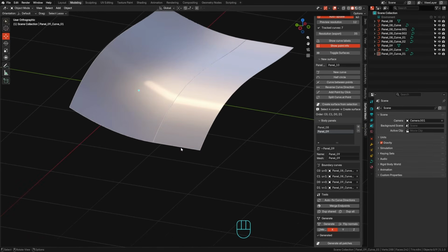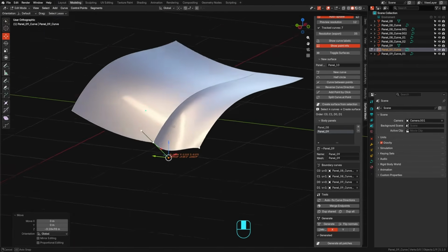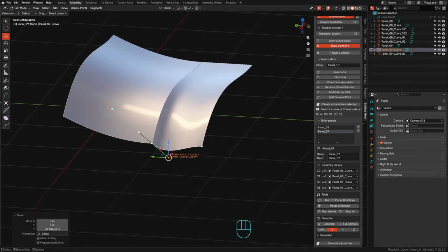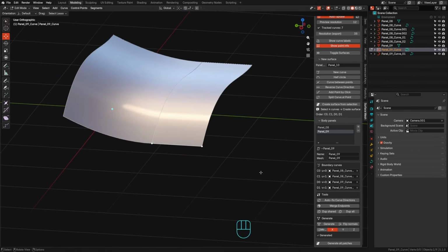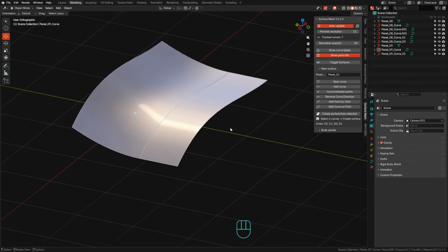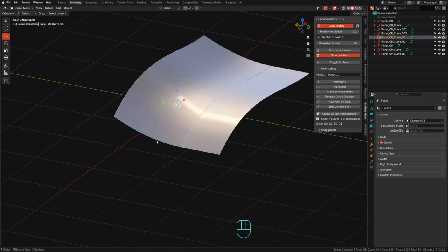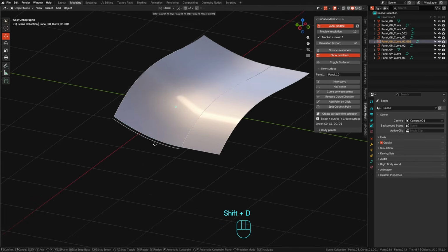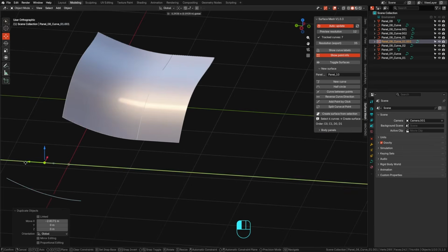However, you can manipulate this shape in various ways and adjust the forms, such as shaping the creases differently. Yes, that means we can do a lot of things. Let's try extending the panel along the x-axis. This means I'll copy the curve, shift it along the x-axis, and I can even move it arbitrarily to the side like this. Then I'll reconnect the vertices. It's very simple.